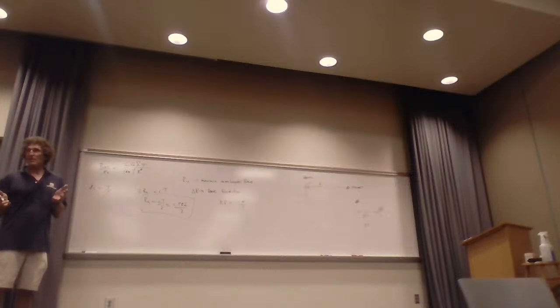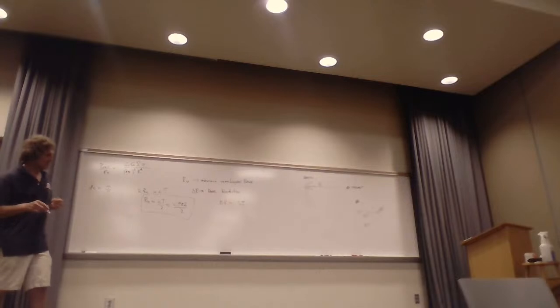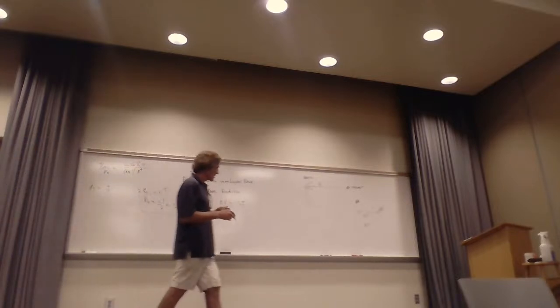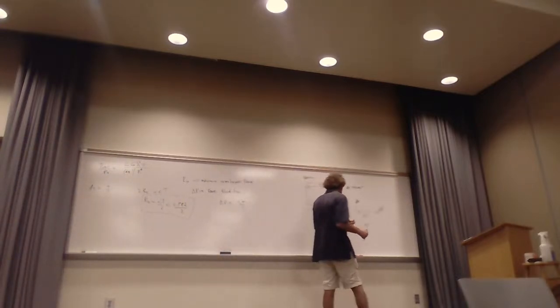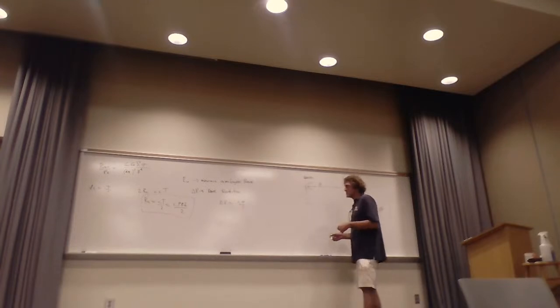They normally are on, and the shorter the time, the better for range resolution. The problem is the average power goes way down when you have real short duration. You want a higher average power. There's a lot more to this. I'm giving you a little background on this because radar is fascinating. So anyway, that would be the range resolution.